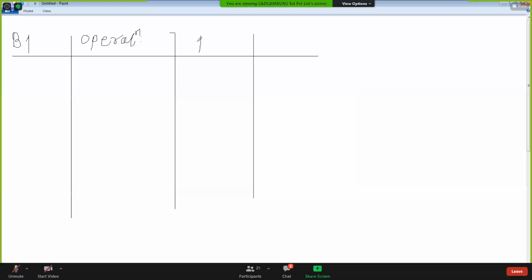Then this is body number two, and you will get the final result. So I create a separate chart to understand well. Suppose body number one is a positive body. Positive body means whatever bodies or features are created through material addition commands. And body number two is also positive.